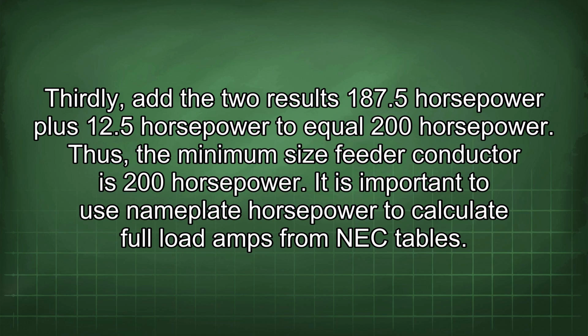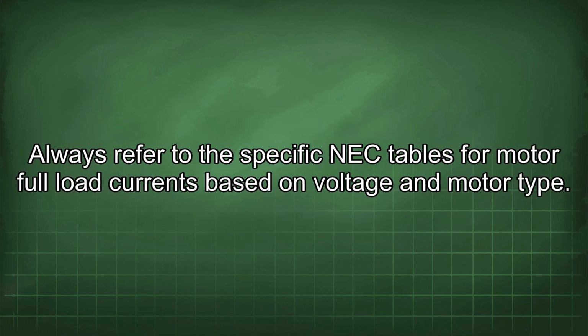It is important to use nameplate horsepower to calculate full load amps from NEC tables. Always refer to the specific NEC tables for motor full load currents based on voltage and motor type.